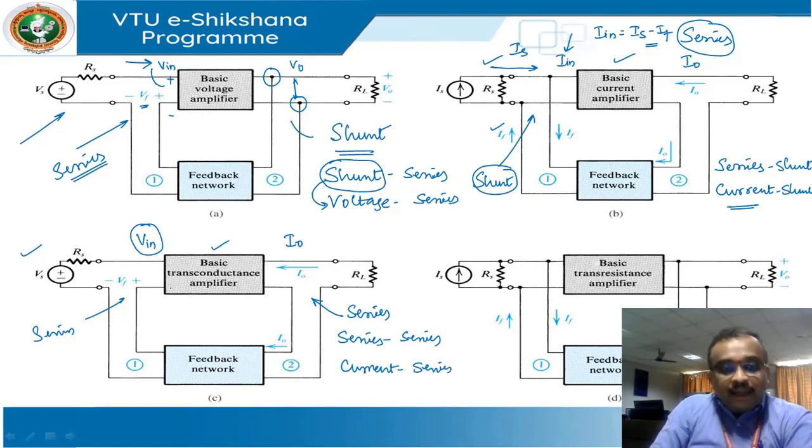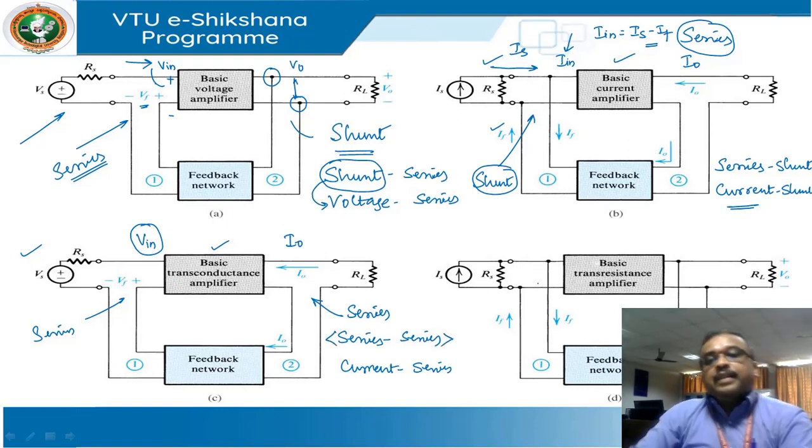Or we can as well retain the name as transconductance amplifier, but with this kind of feedback, series feedback. Okay. Lastly, we have got this. What is it? A trans resistance amplifier. What do we have at the output? We have a voltage value. What do we have at the input? Remember, it is a resistance. So output voltage versus the input current. Its output voltage by input current is what is the trans resistance amplifier gain equation.